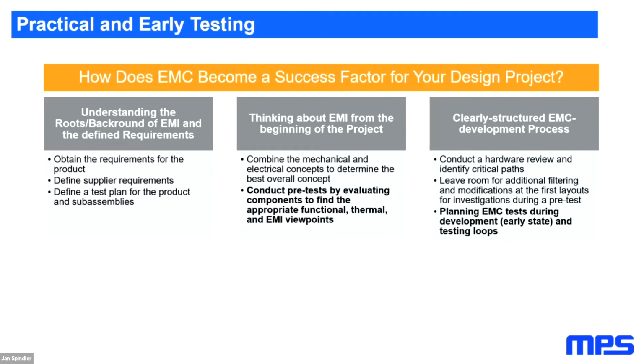You cannot try something, or it takes a lot of time to modify your board to check something, additional components and so on. So that's why it's often good in the first step to have some placement options, some room where you can put a cap or something else in.